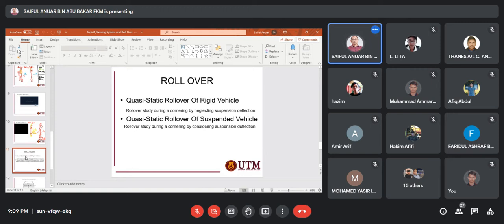They have a suspension system, it's just that it uses a very stiff setting, meaning a hard spring and a hard shock absorber. What I mean by hard is that even though the suspension is installed in the car, whenever you push down on that corner, it won't affect it at all. The car won't move down.